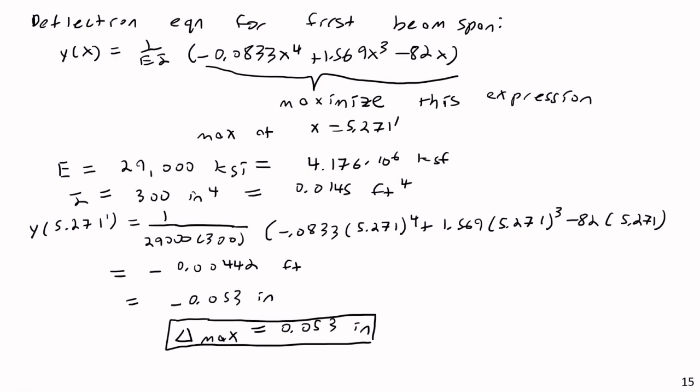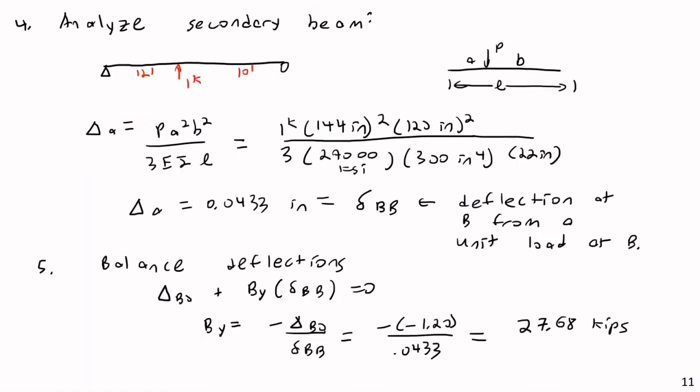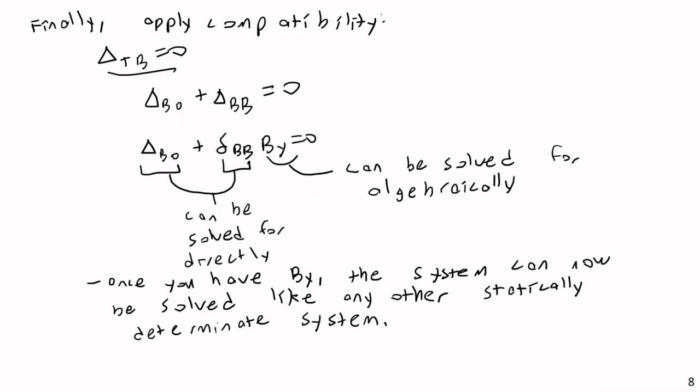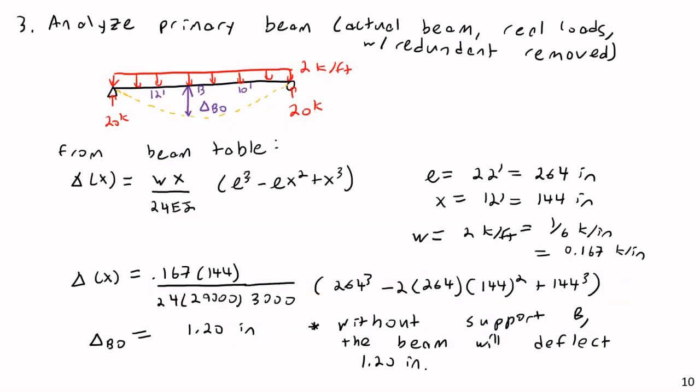And really the reason for this is that while deflection and load have a linear relationship, deflection and span do not. If you look back at these equations, deflection tends to increase with a third power of the length of the beam.